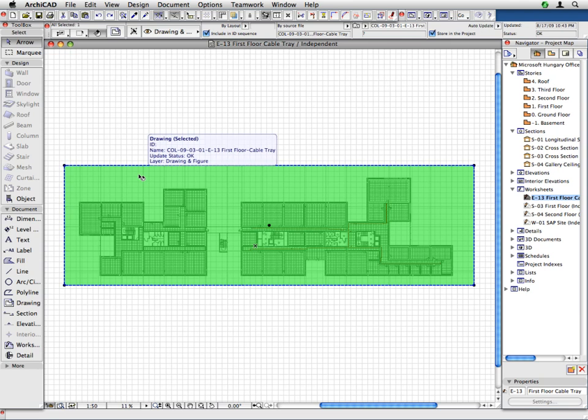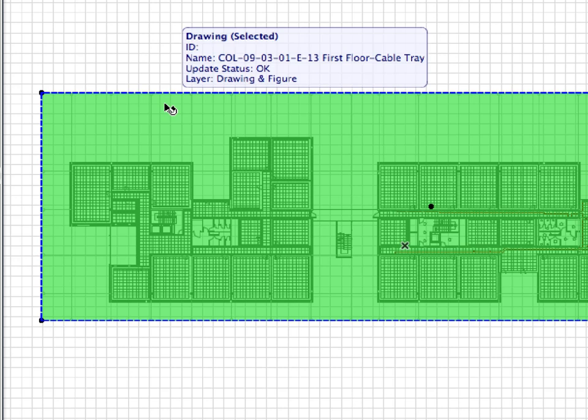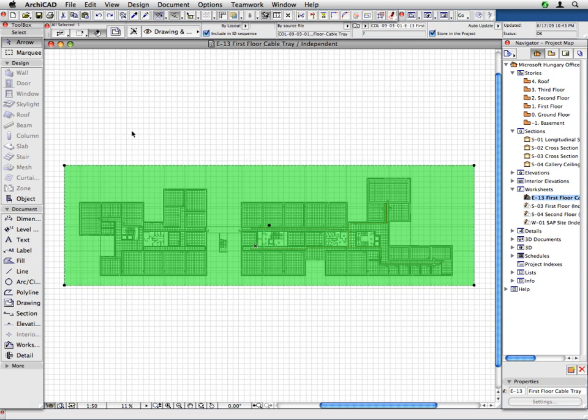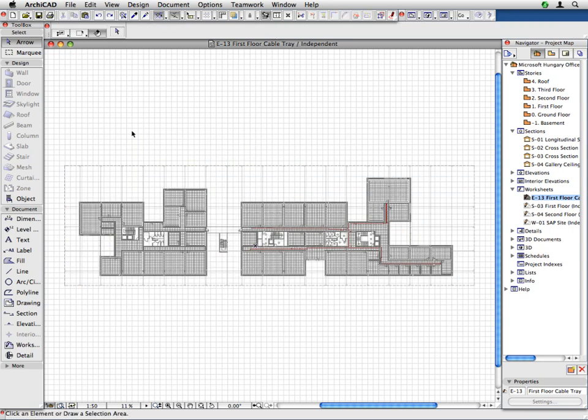One of the most important purposes for placing external files this way is to guard our original attribute set and avoid attribute pollution. Attribute pollution is the unnecessary increase in attributes due to the placed and XREFed DXF DWG files. When we place a DWG file as a drawing, we do not get many unwanted layers and other attributes. When exploding a drawing, all elements of the DWG file can be transferred to a single layer, as you were able to see in the previous steps.